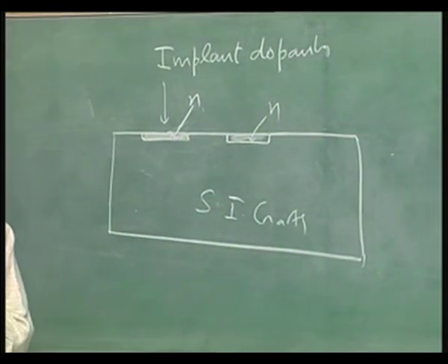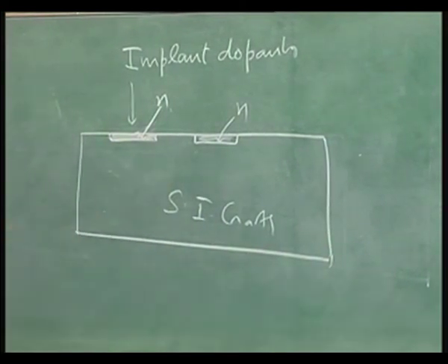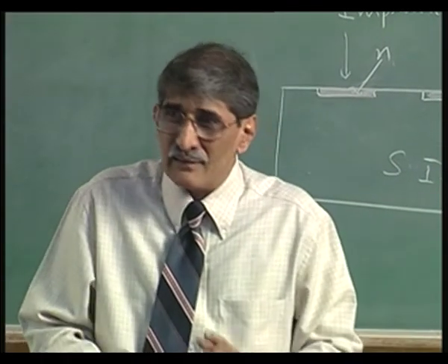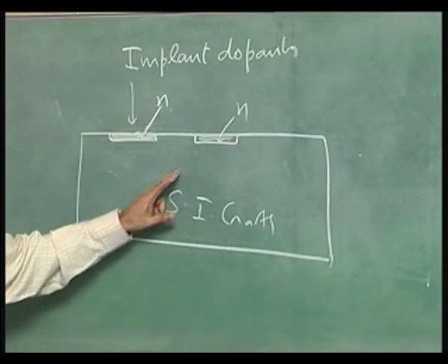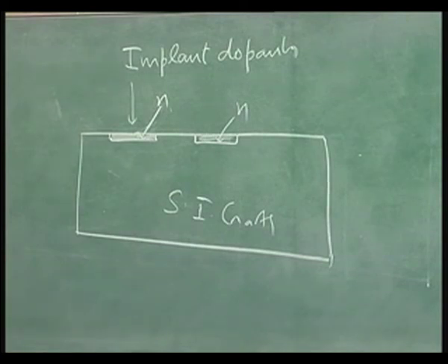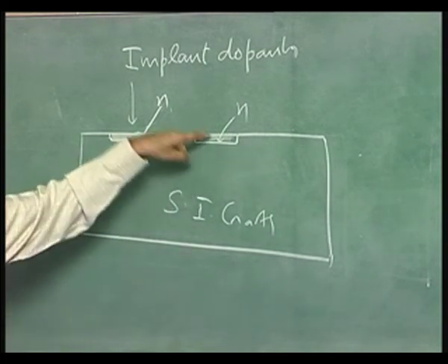You can see the interesting part of this is you have got n type here, n type here, isolated from each other. You can't ask for more than that, because when you want to make devices, you want them to be isolated. Basically, you want them to be connected when you say it must be connected. Otherwise, they must be isolated. The isolation is provided by this particular layer, semi-insulating material. So, if you have an ion implantation equipment, you can use that totally for realizing these structures. All that you would need is the ability to implant and realize this, and then make devices on this.